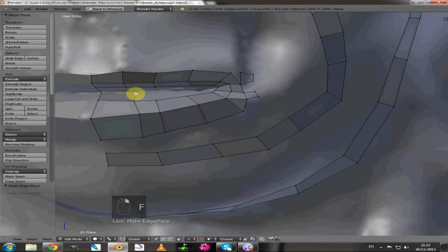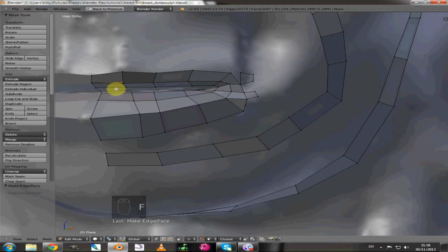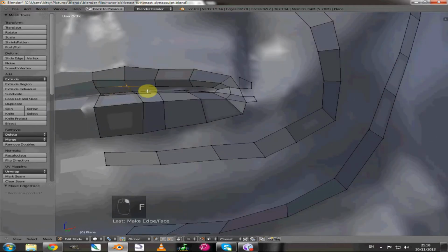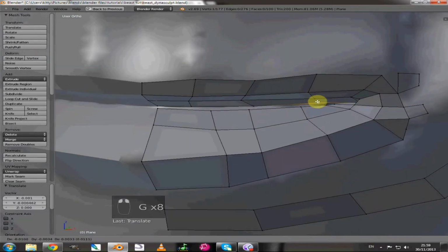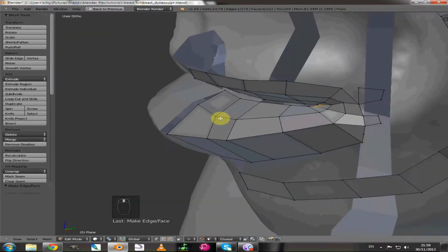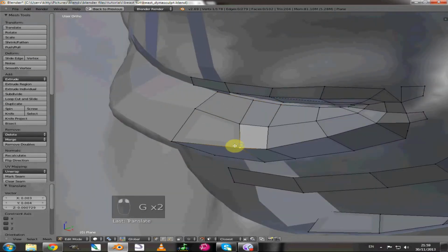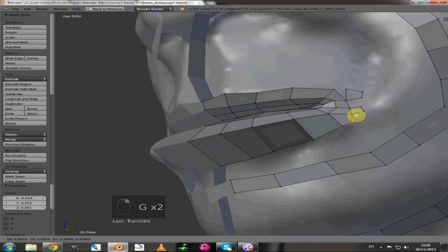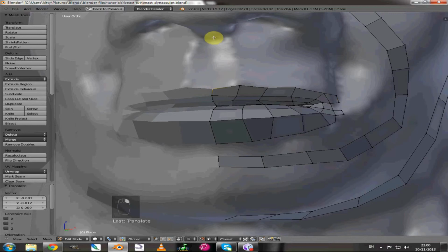There we go, just fill those. Now using the F2 button, I can simply click the corner vertex of each face and press F, and that just pops a face between the three vertices, which is a lot simpler than selecting every vertex you can and trying to fill a face, extruding individual vertices to create a quad and then fill in the face. It's one of those handy little tools that they've applied to the Blender tool set, and that's called the F2 add-on.